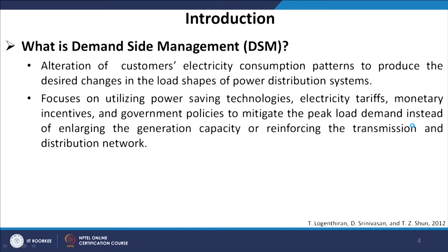That means instead of increasing your generation or your reinforcement of transmission and distribution, if you can mitigate the peak load, that is, minimize the peak instead of putting in new generation to meet your new peak, that is demand side management to us.